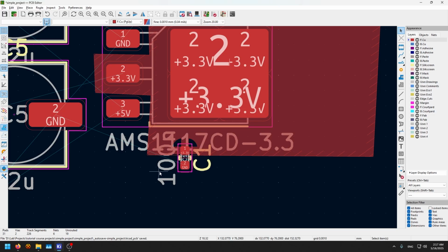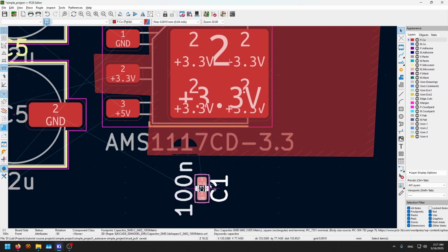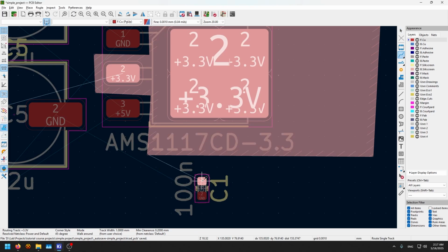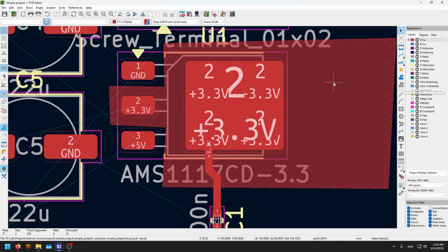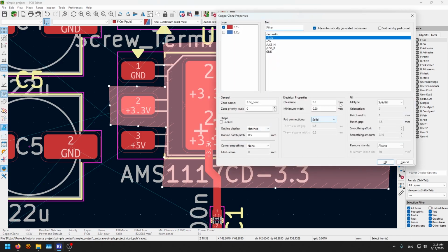But basically, you can just remove this here, click pour, and connect it with a track. Let's put the track to be like half a millimeter. And that's it. Maybe you can do that if it's not really required to be very close. And what else is there to explain? And okay, maybe this is all that's needed.